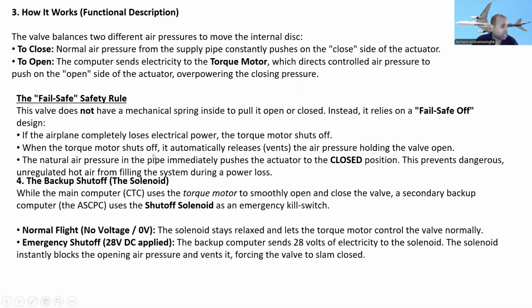When the torque motor shuts off, what happens? It automatically releases the air pressure holding the valve open. Then the natural air pressure in the pipe immediately pushes the actuator to the closed position.